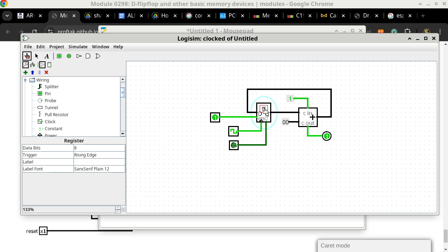So if I turn it to FE, then we'll take one more step to do it. When it's FE, this will be dark. And then the moment I click this one more time, the register will update to FF, which means we have FF presented here, 0, 0 over here, and a 1 here, which basically means we end up with FF plus 1, and that will turn into a 1. So we'll take a look. That's exactly what happened.